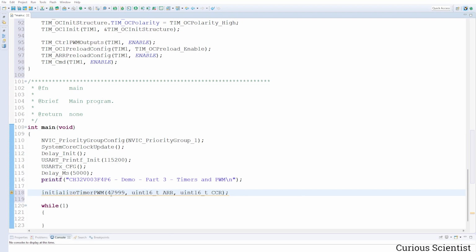So now we know that our frequency will be 1 kilohertz, and then we can determine, okay, how long we want to count up. And 1 kilohertz is exactly 1 millisecond period. So let's say I want to count up to 200 milliseconds. So that will be 199 because of the +1. And then I want to have 50% duty cycle. So there actually I have to put in 100. So if I did everything correctly, this will initialize the timer.